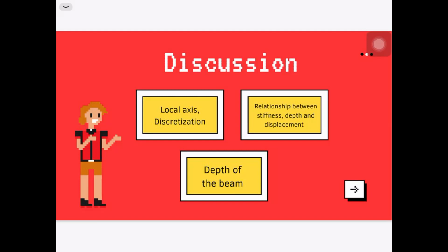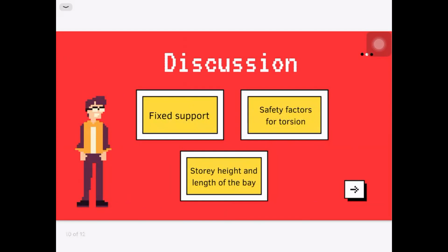And next, why are fixed supports used? As concrete is used in the design, fixed supports are used for the entire building because the characteristics of concrete are similar to a rigid joint, which is unmovable and unrotated. On the other hand, for steel, nuts are used. Therefore, steel is movable or rotated. That is why we choose pin joints for the steel structure.